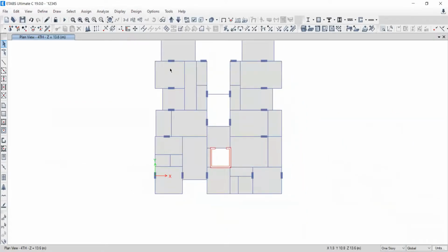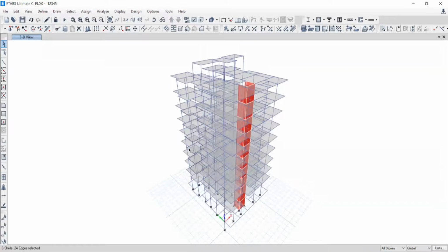So I want to select all the slabs of my model for this position. You know that in the previous case, we have seen that we need to go to selector, then select the floor slab, then go to deselect and all. So many steps are there. So the option is what? If you are taking all story, and you click over this, see, all the models is going to be selected.